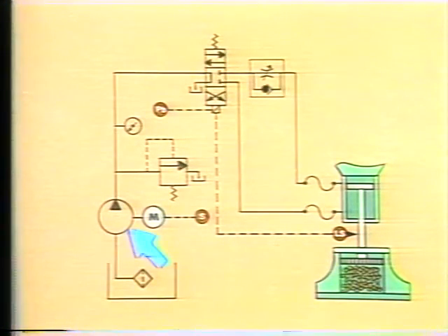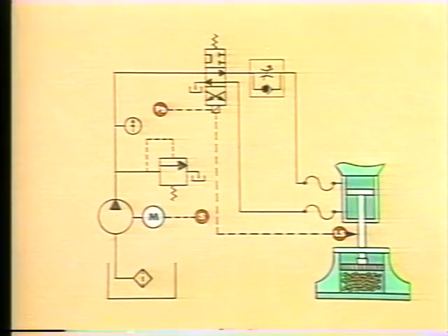When the motor-driven pump is started, it pressurizes the system. The pressure relief valve maintains the proper system operating pressure. To activate the crusher actuator, this push button is used to send an electrical signal to the directional control valve. The signal causes the valving mechanism to move, allowing fluid to flow into the space above the piston. The pressurized fluid pushes the piston down.